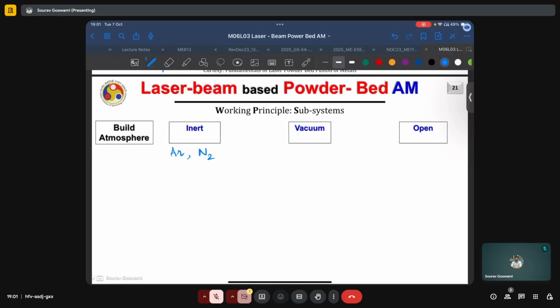They can transfer this kinetic energy to the target material. However, being so light, if in their path they encounter a heavier molecule or some other obstruction, they can very easily get deflected and dispersed. And so it is essential to ensure that the path of the electron beam is clear, and this is ensured by having a vacuum.